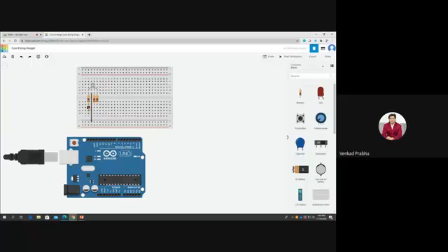For the red one, click inside the breadboard in the same row, on any free pin slot, go out and click to take the bend, click again, and move it and give it to pin number 10. Click it, turn it, and click it into the pin slot.